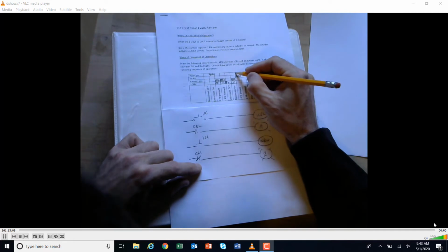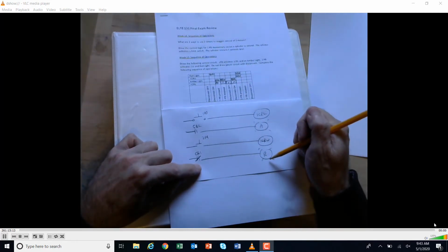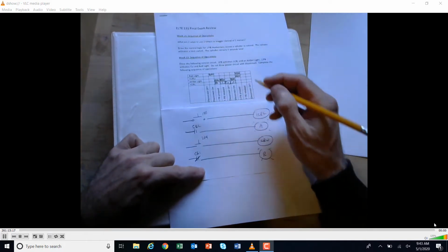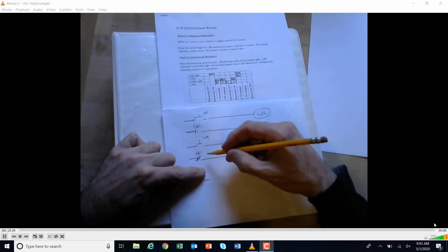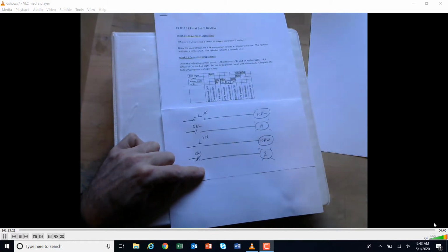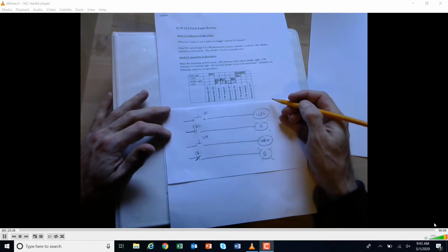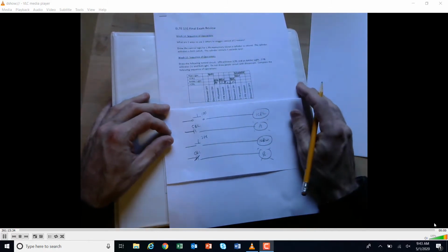This red light would come back on, that's right, because it was closed. 2 PB released. This right here is no longer going to be energized, so it's just going to be off. My red light is still going to stay on because the power is off. And then if I kill the disconnect, once again, everything goes off. So that's the sequence of operations there.